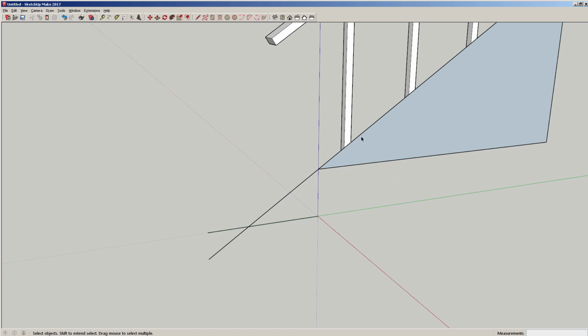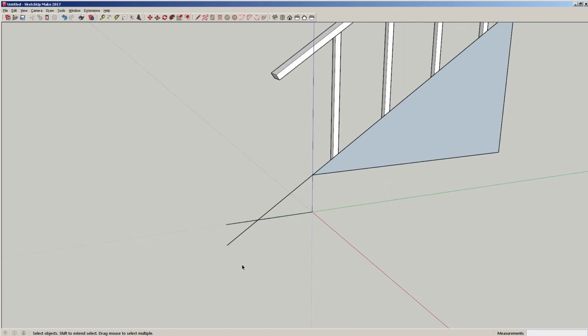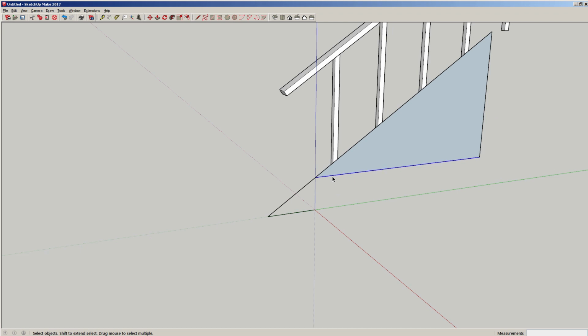And there's something else I haven't taught you. You can trim off these extra lines just by using the rectangle. See how they're blue? Hit delete. In fact, I can trim these off. Delete. Keep it on the blue axis. Now what we don't want is 2 lines here, because as you extrude, it'll create a line. I know I said extrude, but as you press and pull.